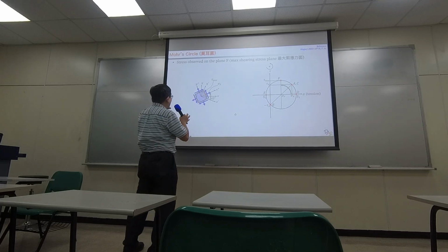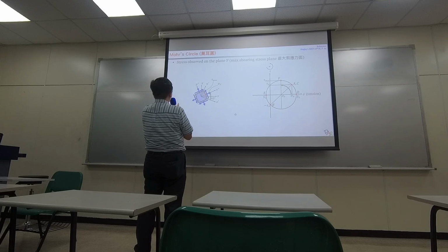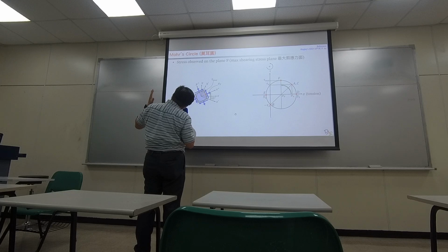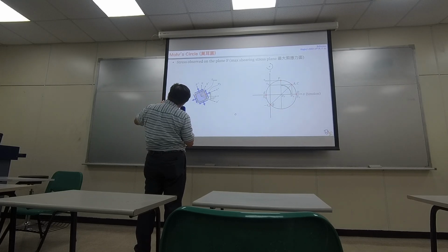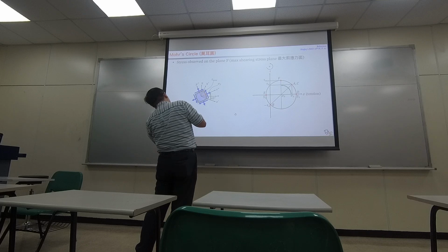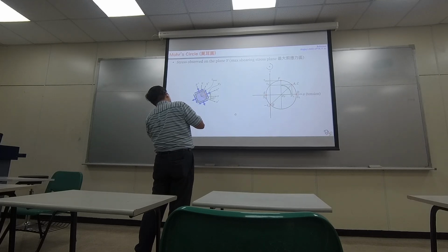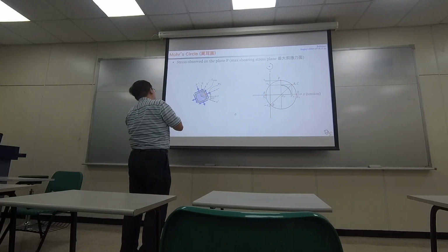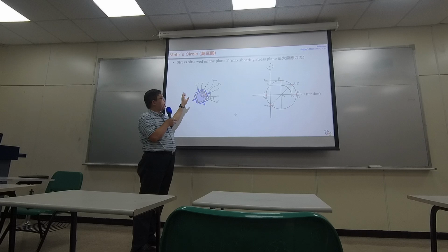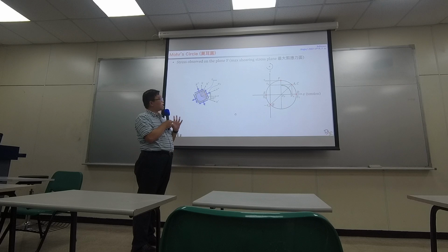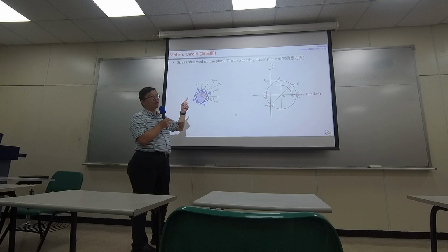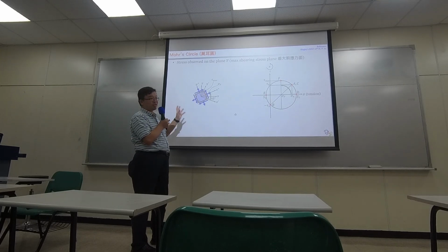So originally we are viewing the element straight. I turn a little bit to find out that along this angle, I see the largest normal stress. Now I turn the coordinate by 45 degrees again, then I observe this kind of loading condition in this orientation. And I realize if I observe the element in this way, at every edge it's carrying the maximum shearing stress. And maximum shearing stress is very important for our design as well.